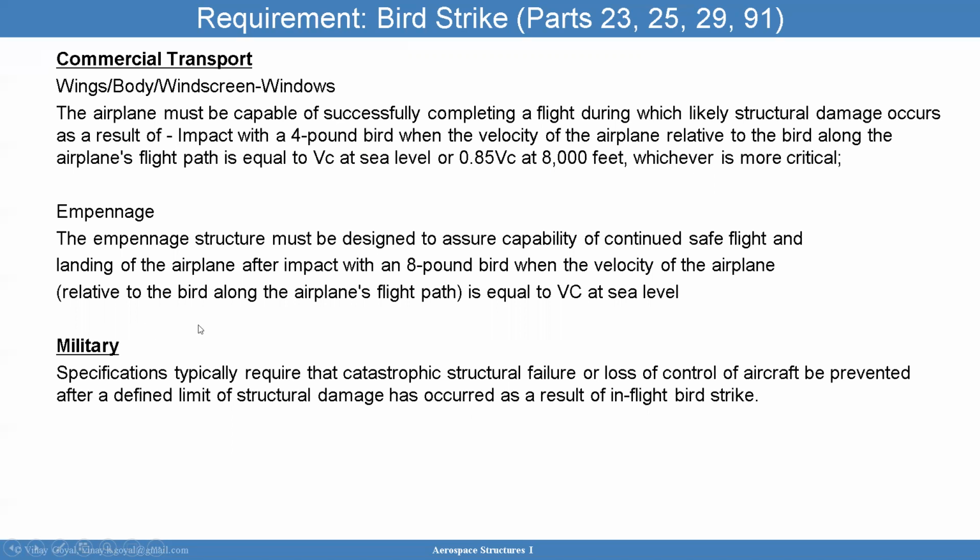critical. The empennage of the structure has to be designed to assure capability of continued safe flight and landing of the airplane after impact with an 8-pound bird when the velocity of the airplane is equal to cruising velocities at sea level. So this is very important. Some of this is done through testing, and then military has their own specifications. I'll let you pause the video and read that.